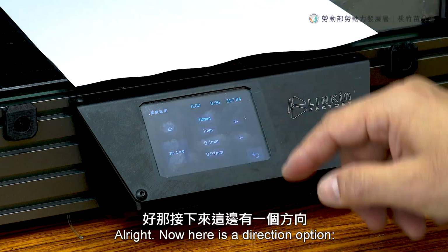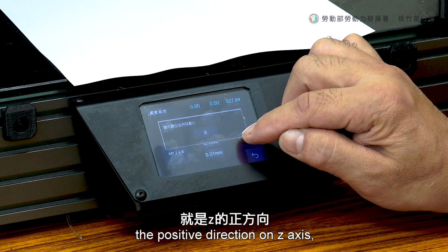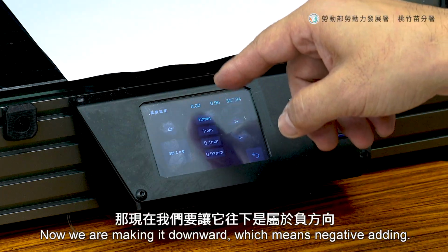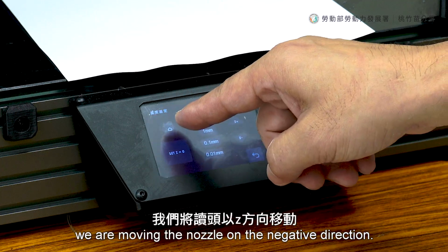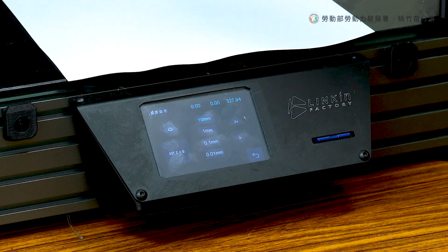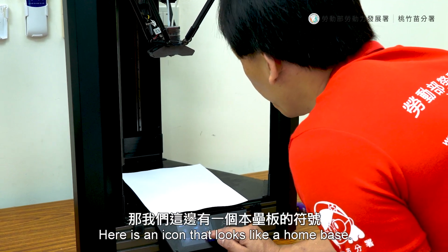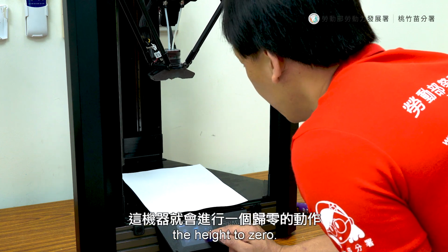So here is a direction option, the positive direction on z-axis and negative direction on z-axis. Now we make it downward, which means negative adding, so now we are moving the nozzle in the negative direction on z-axis. Okay, now a hint. We will need to reset the height to 0. Here's an icon that looks like a home base. Press it and the machine will reset the height to 0.